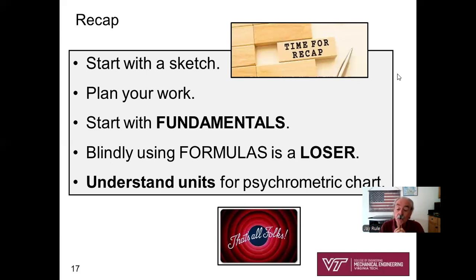In looking ahead toward quizzes and tests, your instructor may instruct you, I want you to solve this using the psychrometric chart. So therefore, you got to get good at it. Instructor might say, I need you to not use the psychrometric chart and use an analytical approach, or you may be free to use either. You do have to remember that psychrometric charts only apply to system pressures of 1 atmosphere. So that's another key thing to remember.